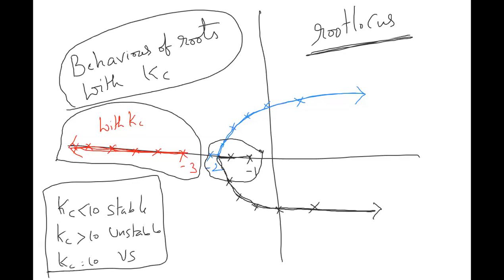which tells you whatever Kc you get from the Routh criterion table or frequency response. Frequency response does also the same thing. It tells you up to what Kc the systems are stable. So you might get, let's say, 10. Because I want higher Kcs? No, you are always looking for higher values of Kc, because higher values of Kc have two potential advantages. One is it increases the fastness of the response. Second, it eliminates the offset.